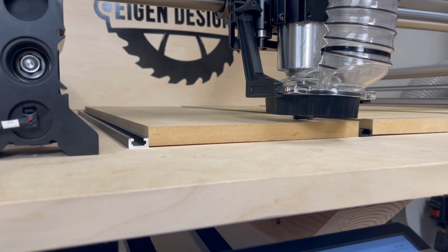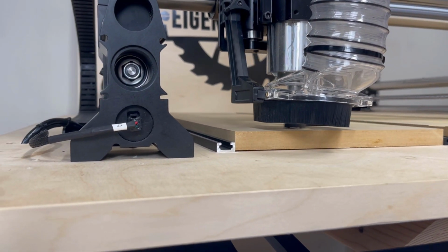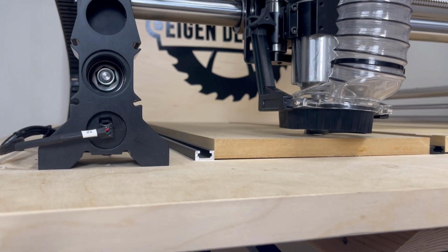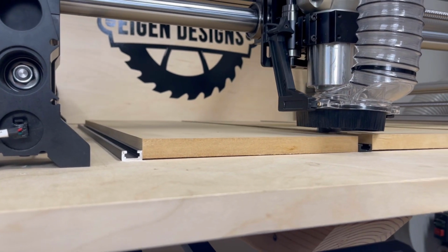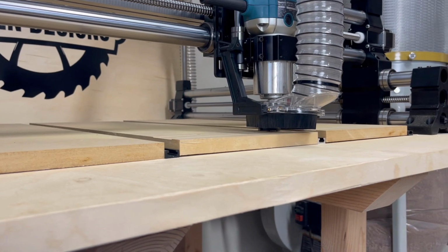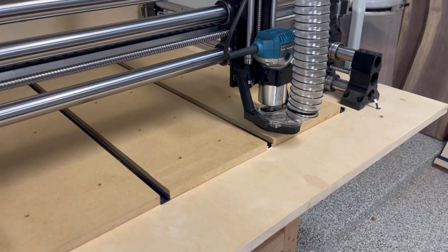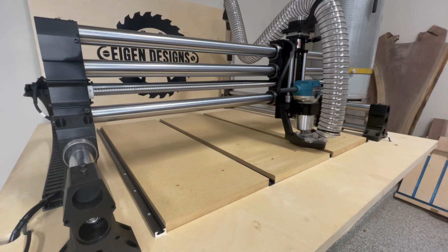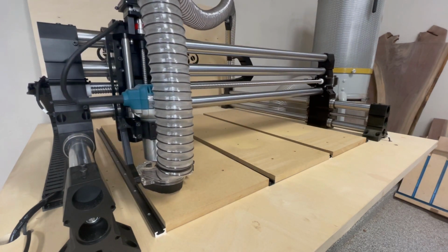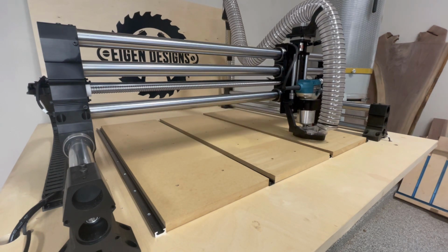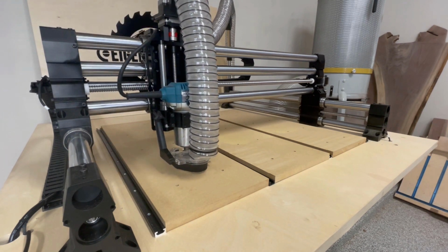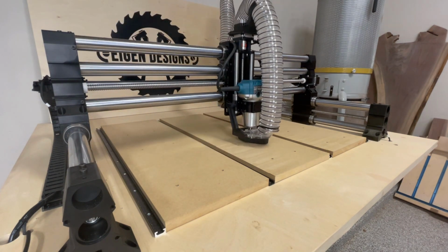You'll also see that the cutter is not cutting along the entire tool path, which just tells you that the boards are not level with one another, and so you end up having to take incrementally deeper cuts to make sure that you're actually cutting all parts of the wasteboard. That's the only way that you can verify that every piece of that wasteboard is flat and parallel. So there's a few iterations of this particular step, but it's pretty straightforward, and it's a really good introduction of how to actually use the CAD software, the CAM software, and how to run your CNC.